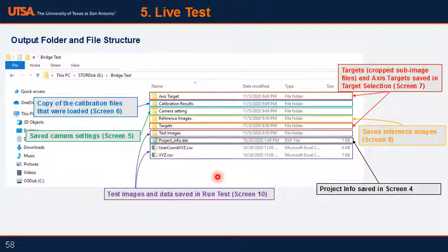And finally, last but not least, these are the CSV files. These are just basic spreadsheet files. You can open them in any spreadsheet program. The basic xyz.csv file is the XYZ coordinates of all the targets you've selected in the left camera coordinate system. That is the default. This file is always generated. And if you have selected 3 targets to produce a reference axis, then the user coordinate XYZ file gets created. Usually that's of more interest because it is lined up with your structure. This is your own coordinate system.